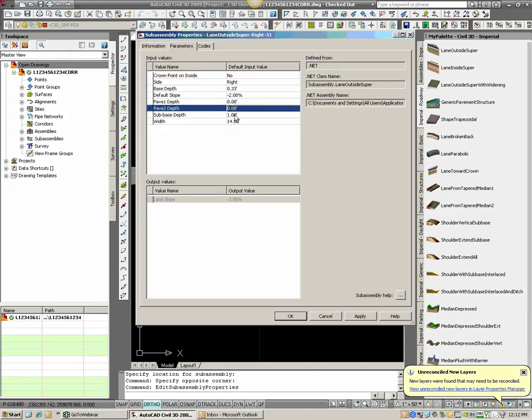all the pavement thicknesses. But at this time, I really don't know that. It's very conceptual, very beginning of the project, so it doesn't really matter. I'm just going to let them go. I can set those at any point in time since everything's all dynamic. They'll switch if I do cross-sections. Wouldn't normally do that on a residential project, but if I do cross-sections or quantities, you can switch these at any time and it would update everything.